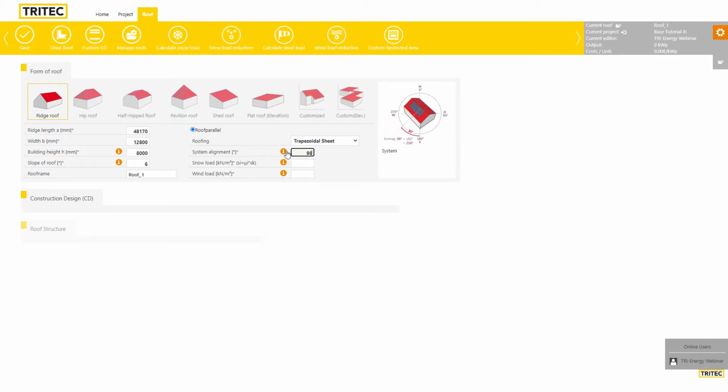And once you hover over this little eye icon here, you see an example. Let's say if in the regular solar branch, you wanted to type in 30 degree into the example, you need to add 180 because south is 180. So the input that you need to do would be 210 degrees. So in our case, it's 89.